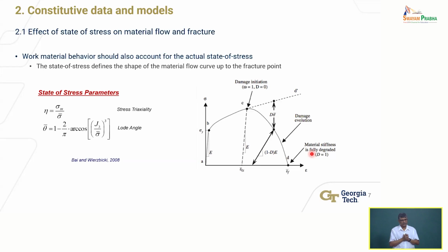So they are called yield criteria. There are two commonly used, and you will learn about them if you haven't yet, called the Tresca yield criterion or the von Mises yield criterion, etc. These criteria basically tell you when you apply some combination of stresses to the material, will it exceed the yield strength of the material in tension, compression, or shear, depending on how you're defining this, right? So such yield criteria are required. Now, having that general understanding that there is a way for me to quantify, the state of stress is important for that reason. Will it yield, not yield, okay?